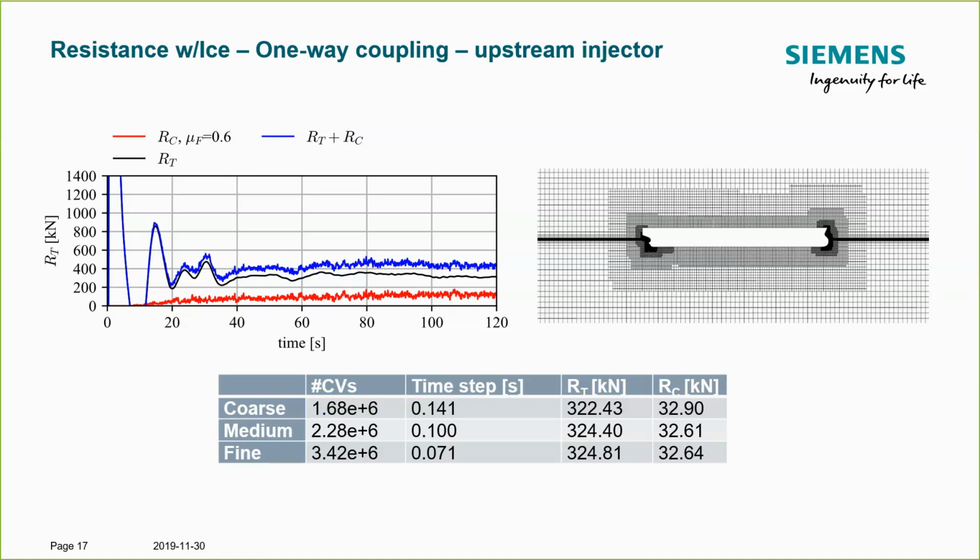But also, let's not forget that if we globally refine the entire mesh, we will also change the discretization of the hull surface. In the end, the contact forces will be constituted by the contact surface that the particles and the ship hull form.